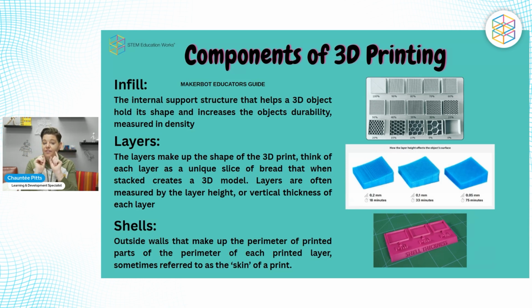It's usually set to 15% as a default. And that's what my printer is set to. So how I do it is I usually leave it on 15% unless I'm printing a bunch of small things. And you have to think about how that's going to impact the smaller you make it. So definitely want to keep an eye on that. You increase that infill depending on what you're doing, how small it is, or what the design is itself.